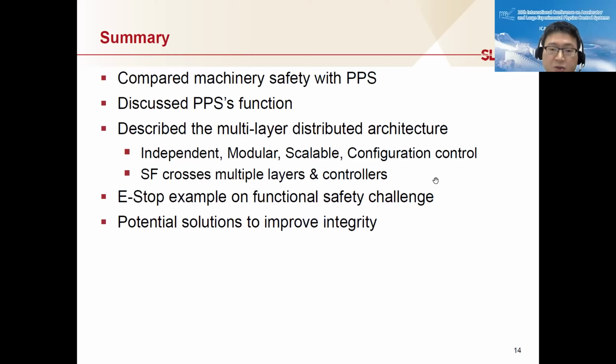But as I also mentioned, because of this approach, when we go to the project review, every technology is proven and there's no big change to the overall architecture. The consequence, though, is that the shutoff chain becomes longer and longer, and then we lose performance on the safety integrity. So that's the motivation for part of this study: why we want to look at the overall shutoff chain, to see if there's any way to compensate for this loss of safety integrity.